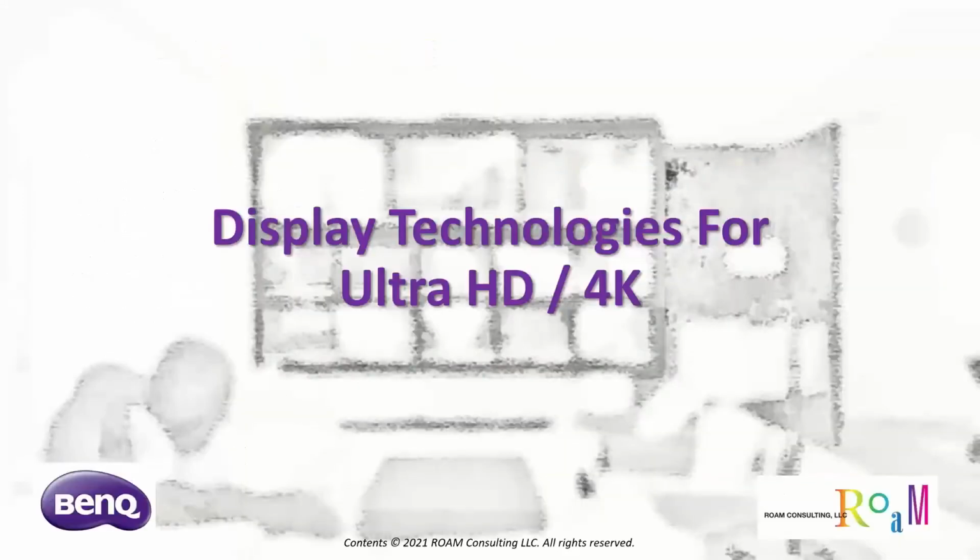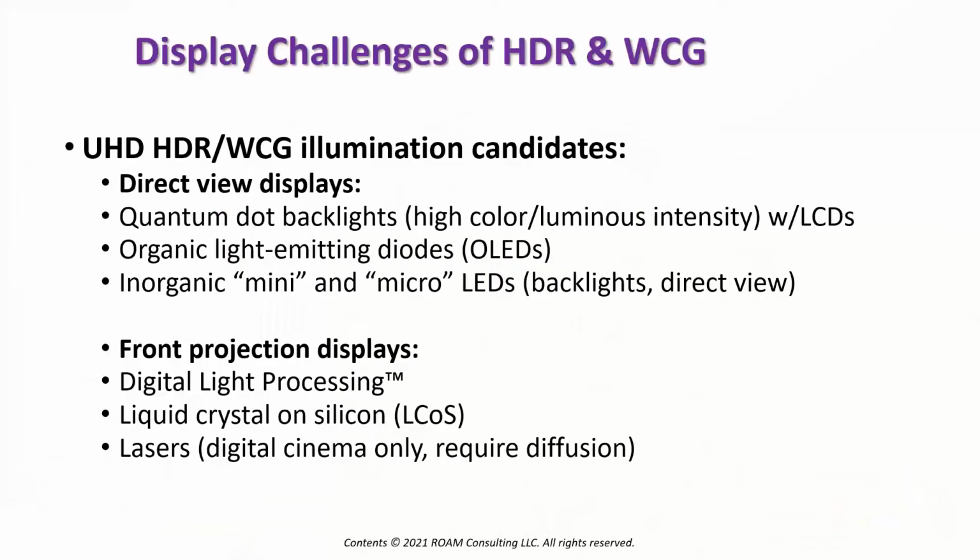Let's talk about some of the display technologies we now have for Ultra HD and 4K. For HDR and wide color gamut, we can't use conventional designs for backlights and LCDs or self-emissive displays. We have to add some horsepower to it. We've got to soup it up. So for direct view displays, there are quantum dots, which you may have heard of, giving high color and luminous intensity with LCDs. This is a very common solution to do HDR on an LCD display. Organic light emitting diodes can't get as bright as an LCD with quantum dots, but they still do a pretty good job on their own. They can get up to about 800 nits, small area white.